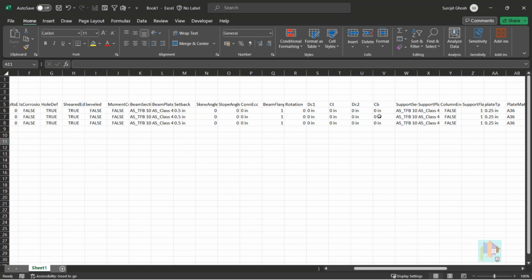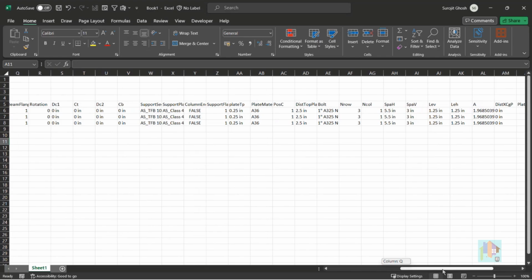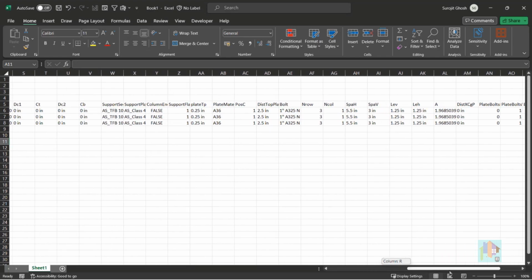I need to find out where the bolt number present here, and I need to change the bolt number. Everywhere it is 3 number of bolt. I want to change this to 4 number of bolt and 5 number of bolt. Copy the data, paste it in Excel, change the name, change the required information. That's all. This is the bolt column, single column.